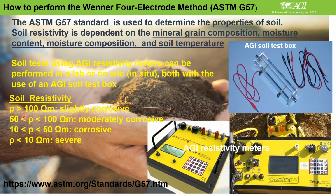So for example, you can decide: if my resistivity value is more than 100 ohm meters, it's slightly corrosive. If it is between 50 and 100 ohm meters, it's moderately corrosive. These are typical standards you may see from the Institute of soil testing.